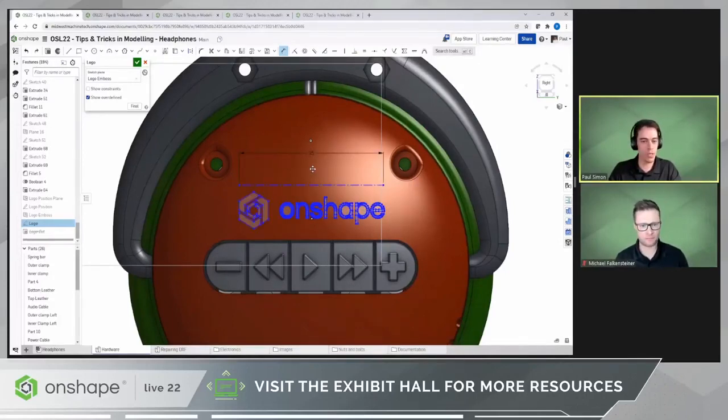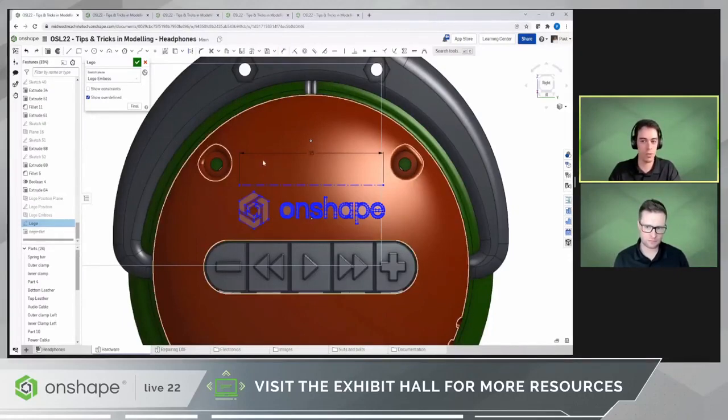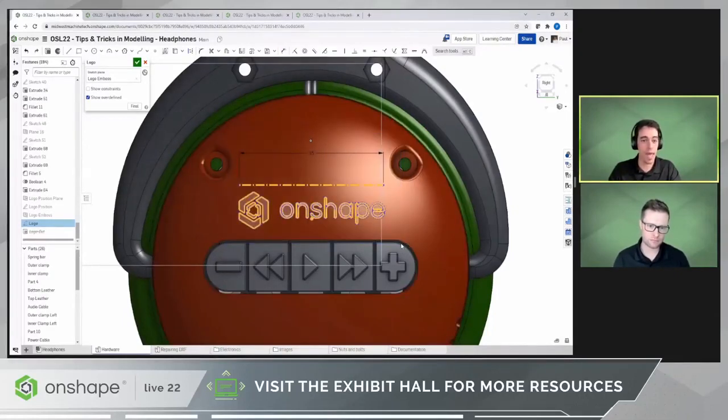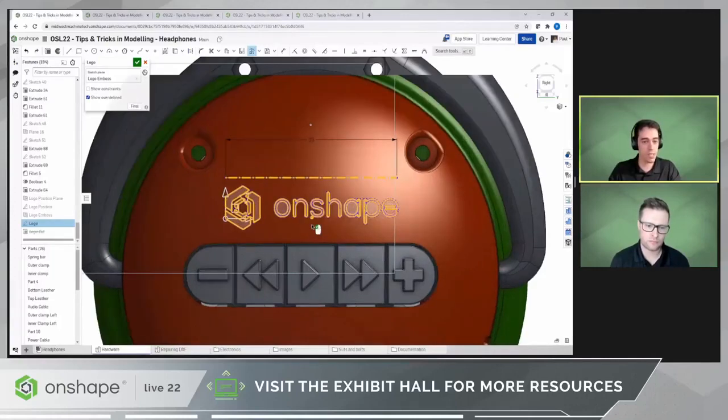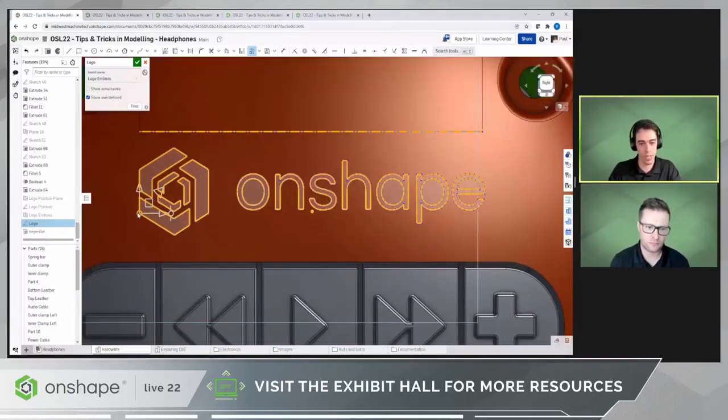Next thing I want to do is to transform the logo and move it to a precise location. So let's use the transform command. I've added this again to my shortcut toolbar. I really like to work with the toolbar. And as you can see, as soon as I do that, the triad manipulator appears. And one tip here that I can give you is that you can move this triad manipulator by selecting the dot and snap it to a relevant point, for example, this S here.